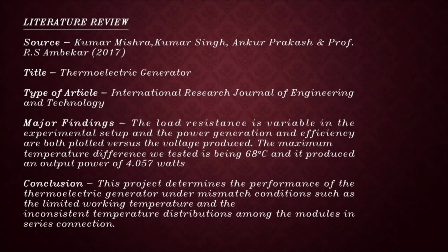The maximum temperature difference we tested was 68 Celsius, and it produced an output power of 4.057 watts. The conclusion of this source is that the project determines the performance of the thermoelectric generator under mismatched conditions, such as limited working temperature and inconsistent temperature distribution among the modules in the series condition.